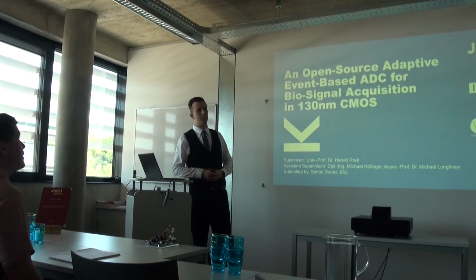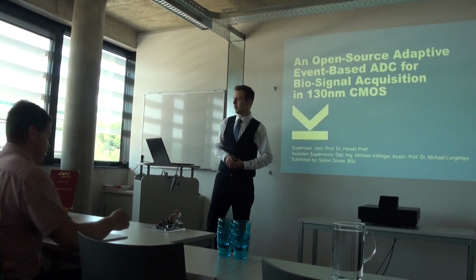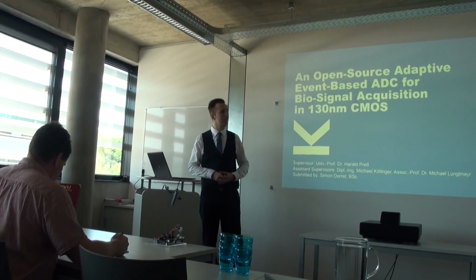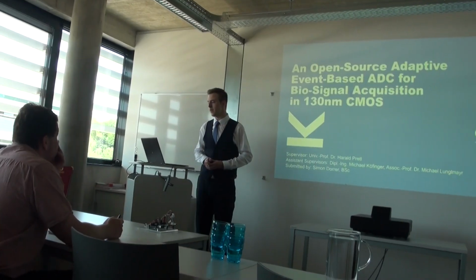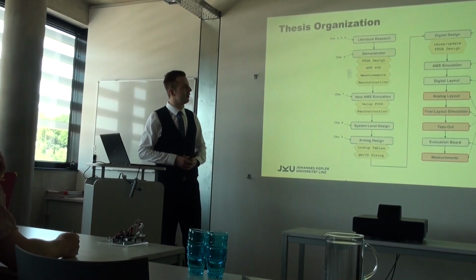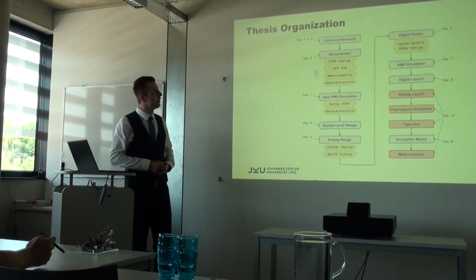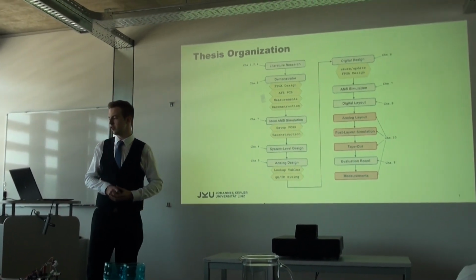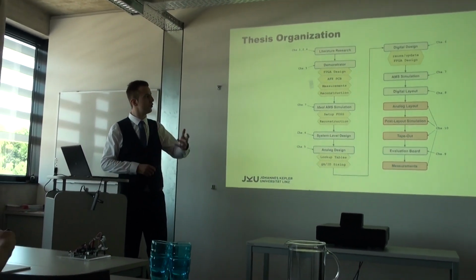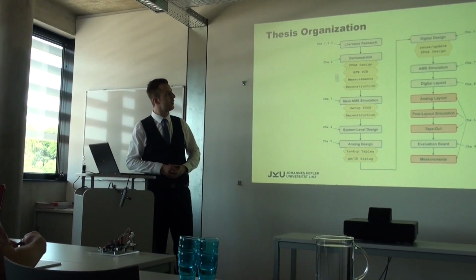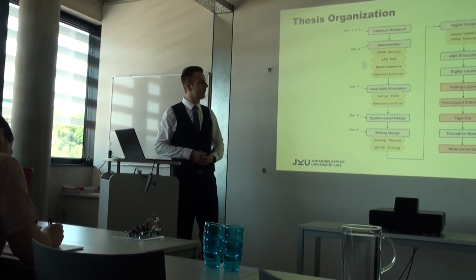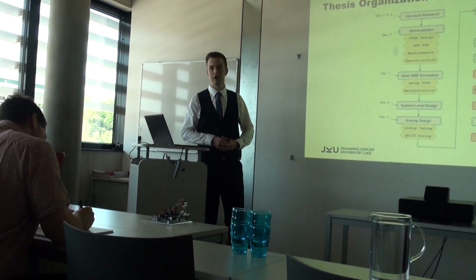Master's thesis presentation about an open-source adaptive event-based ADC for biosignal acquisition in 130 nanometer CMOS. So my thesis is basically structured like you would design the flow of an ASIC. At the beginning I did a lot of literature research, which is for event-based ADCs really important, as I will show you in the next couple of slides. Then I built a demonstrator to prove the functionality,